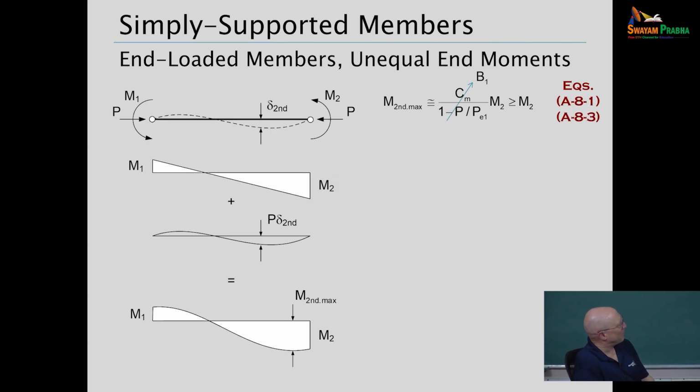Let's look at a case that shows up a lot. I'm showing this member kind of turned horizontal, but this shows up in multi-story buildings, where we very typically have moment loadings that would look like this, right? Reverse curvature bending on the member. Well, in AISC practice, given these first-order moments, where M2 is the larger first-order moment, shown at the right-hand end, M1 is the smaller moment.